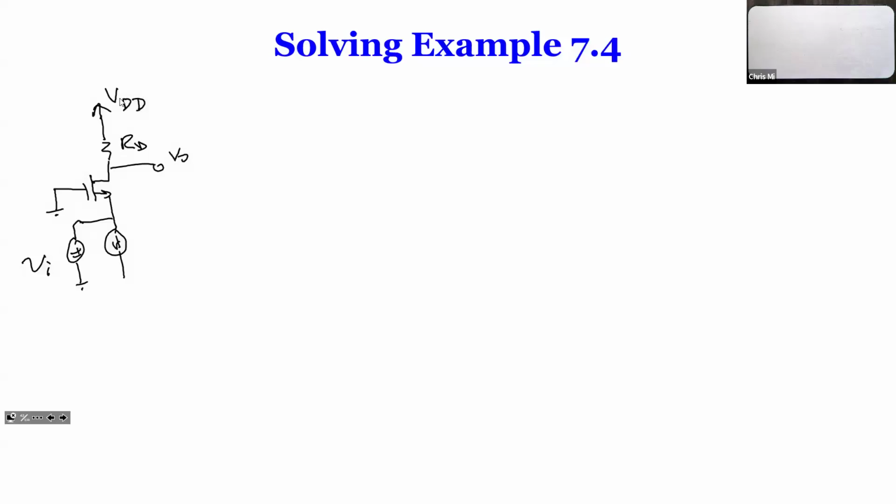There's also a ground. Make sure that we really have an arrow here, which means this current source is pointing to a lower voltage than ground. If you have ground here, and a ground here, it's typically impossible to have a current source with current flowing between two grounds. So this voltage has to be lower, a negative voltage. But anyway, looking at this circuit, first of all, because the input is at the source, the pi model is likely not going to work very well. So that's why we're going to go with the T model.